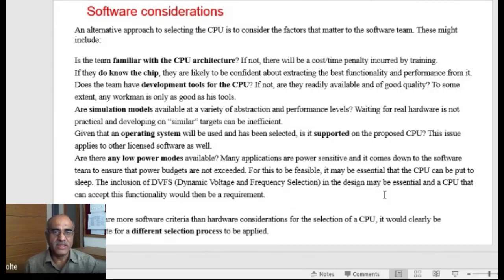Yesterday we went through the different versions of ARM. We have ARM with the T extension, that is with Thumb. Then we have the extension with the S, that is synthesizable. The second one is with the J, that is, Java bytecode can be executed along with this ARM.